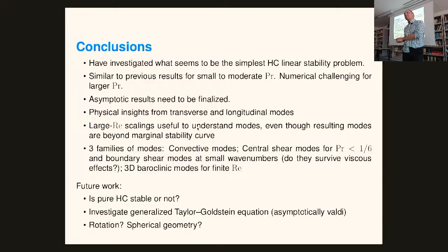And if you're going to idealize it in this way, homogeneous here, the idea is when can an idealized periodic boundary condition problem in a vertical direction resemble the inner part of something that has a top and bottom boundary? And that has to do with, of course, the height, but also the Rayleigh number. In all the things I read, that was a huge deal: in vertical convection, are we in the double boundary layer regime or are we in the conductive regime?